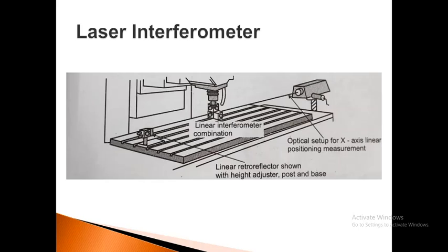The resolution obtained can be 0.01 microns. Such equipment is particularly useful for checking the movement of machine tool tables, aligning and checking large assembly jigs, and making measurements of intricate machine parts like tire tread molds.